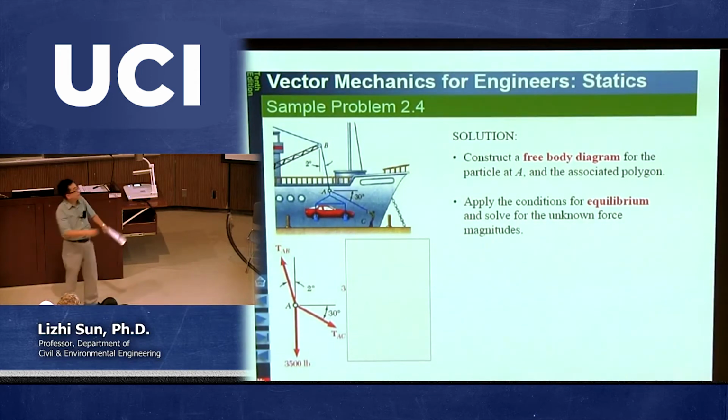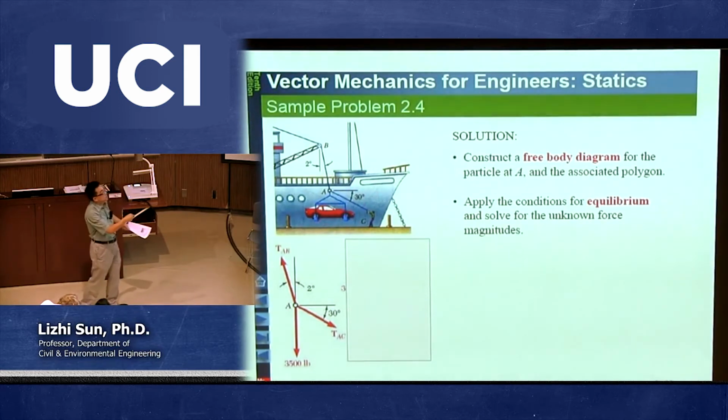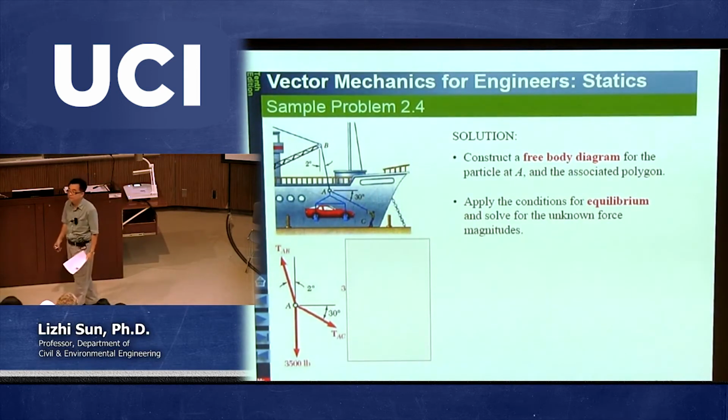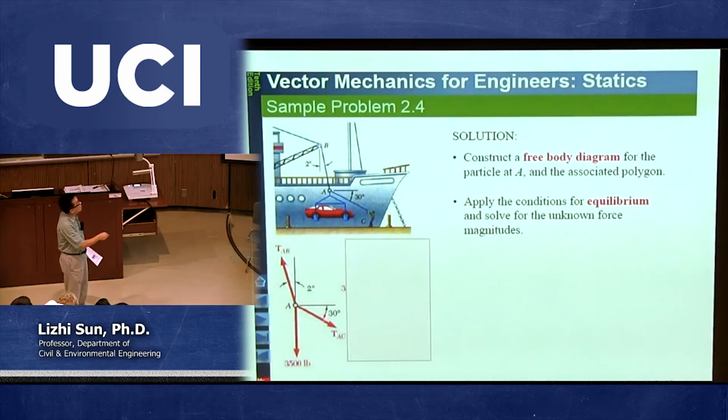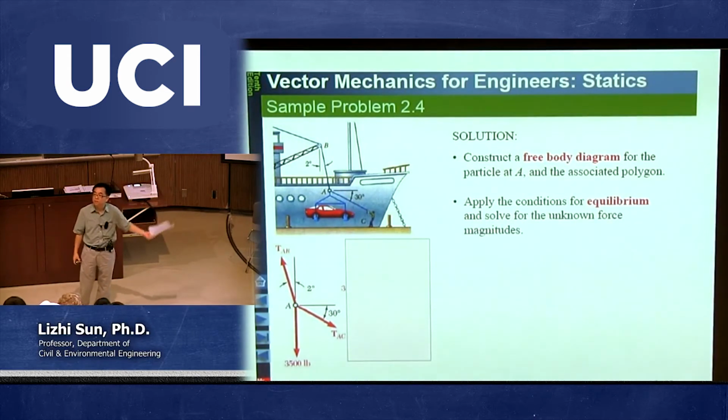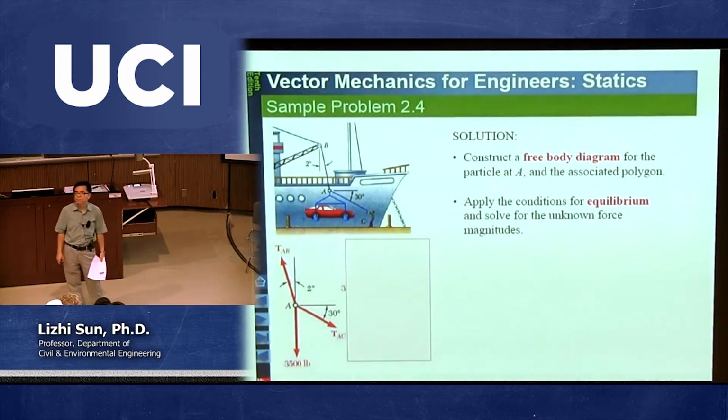If somebody designs something with a reverse case, say, okay, in order to unload this car, this person must provide 3,000 pounds. That's not realistic because nobody can provide 3,000 pounds, one person. So through this way, you can end up with some kind of estimation, assessment, saying this is a good design. You can unload this very heavy car instead of giving a big force, which you cannot. You only need to provide 140 pounds, and that's doable. Okay?